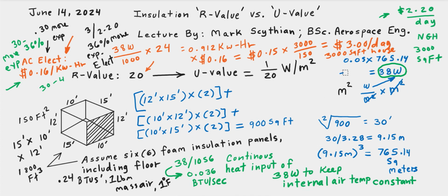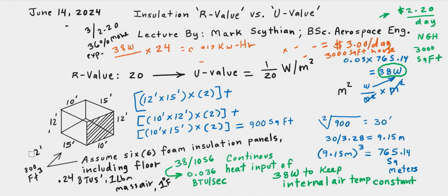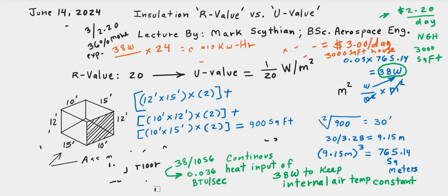So in this case, we can isolate the information in simplicity that when you get an R value for insulation, just find its reciprocal, and that becomes the watts per square meter continual heat requirement multiplied times the total insulation area, all 6 sides, or I would figure the floor insulation could be a major factor in heat loss, so we'll just say it's 6 sides insulated.